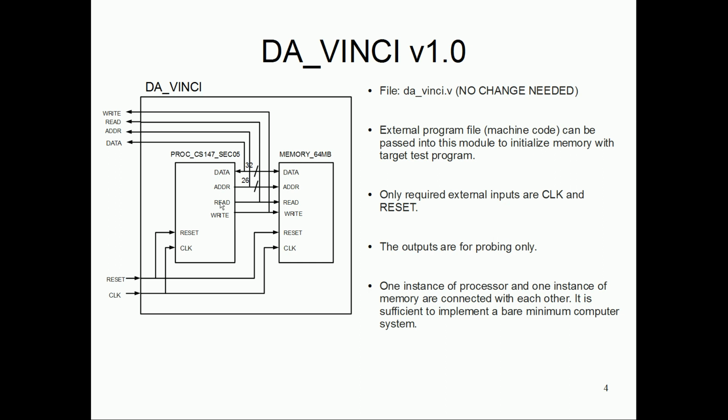Now it parses the instruction and does whatever it needs to do. If it involves a store word, which is how the program stores the result back in the memory, then it issues the store word address where data needs to be written. It pushes out the data and sets the mode to read equals 0, write equals 1. That's the write mode, and the result is written back.